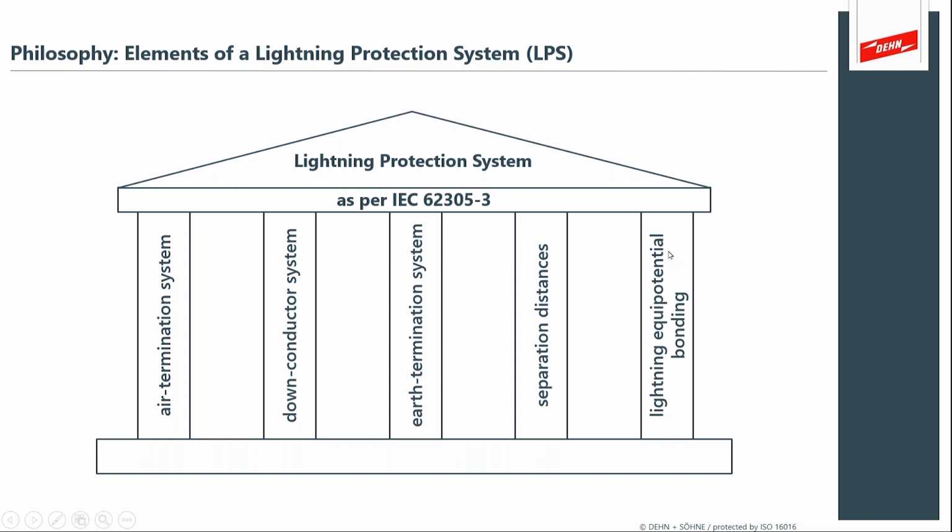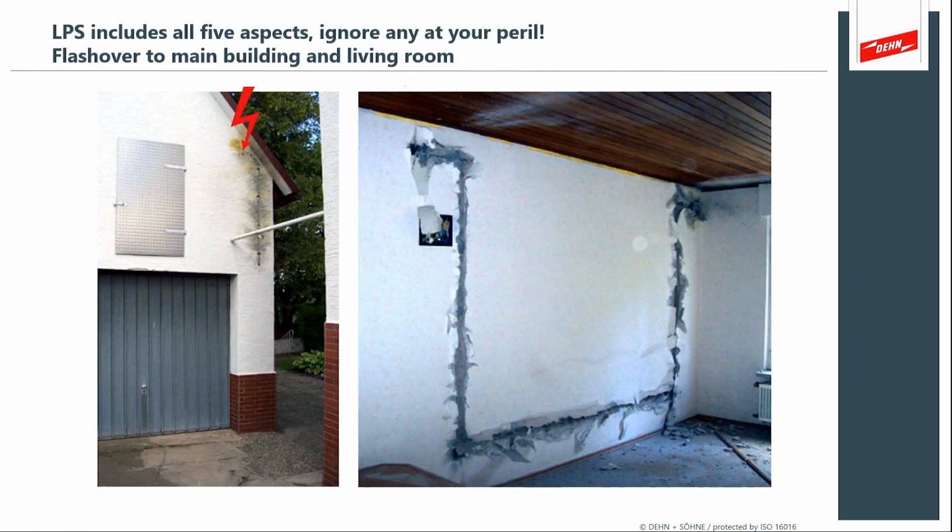And then the last piece of the fundamental pillar of lightning protection is equipotential bonding. So what we say is bond it together. If there's metal, you should bond it so that it doesn't accidentally flash to it. And what's important about that is you'll see in photographs such as this, lightning will flash over into your electrical systems. So you can't necessarily bond your electrical power conductors, so you have to separate them. So that's really what you want to pay attention to.